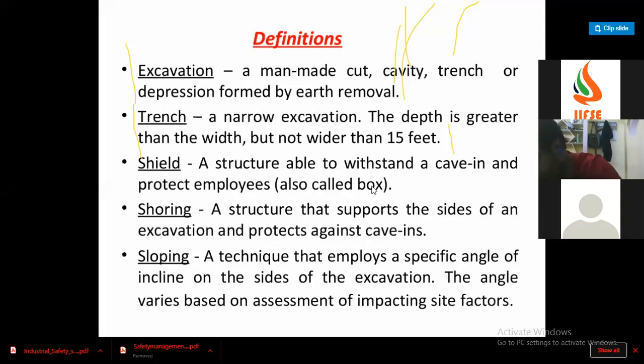Sir, if you're working in an Edco brownfield or somewhere similar, even for half a meter or 2 meters, it's not a matter. Before starting the activity, we need to go for a gas test based on the permit and the requirements. We can't judge the situation; it is based on the situation and the environment, and on the permit requirements.